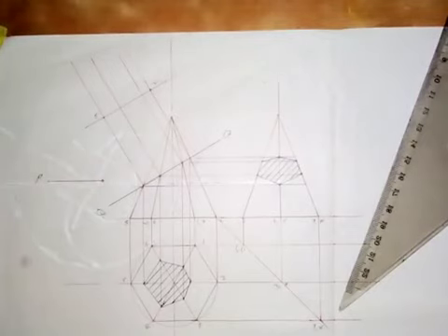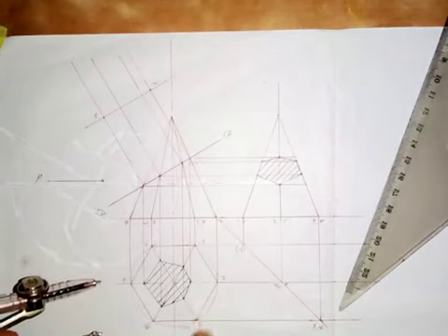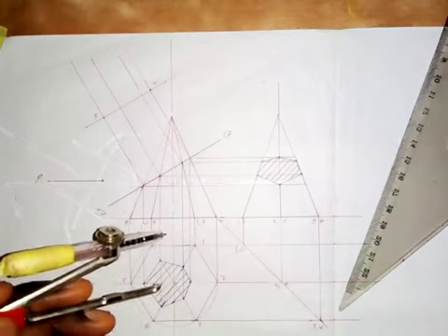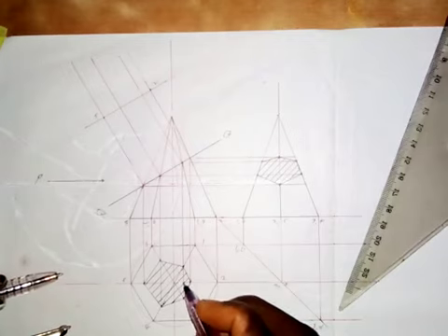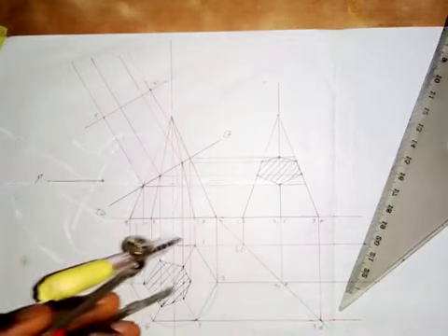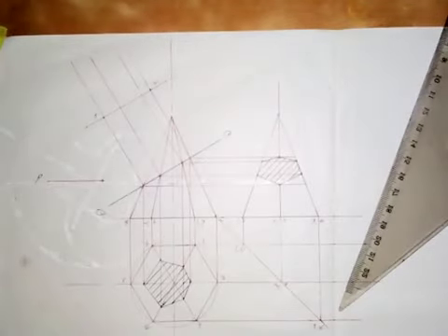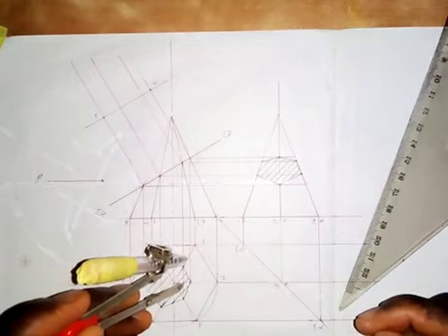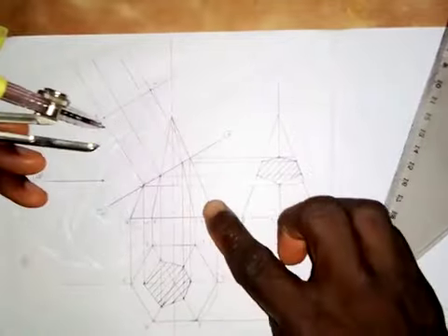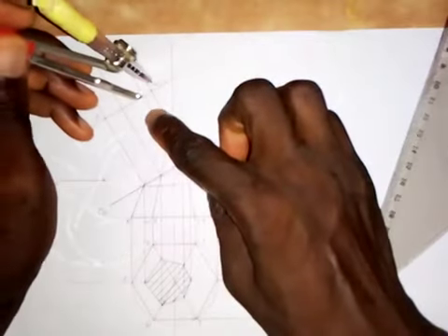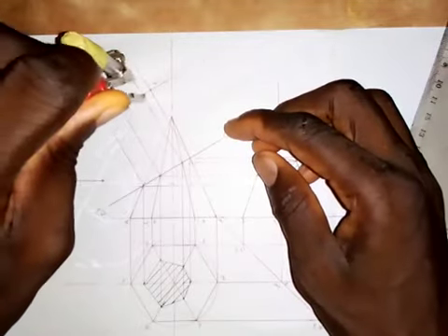So I need to locate the other points, and to do that, I will just take my compass. This line contains 1 and 3. So I'll just put it in the middle, the midpoint. This midpoint that is on the horizontal center line is in between 1 and 3. So I just put the pinpoint of my compass here, and take this distance. I need to reduce this a bit. Okay, so I'll take this distance, from here to here. Then I will follow this line. It contains 1 and 3, so I put it at the midpoint here, and then I'll make an arc at this point, and also I'll make an arc at this point.